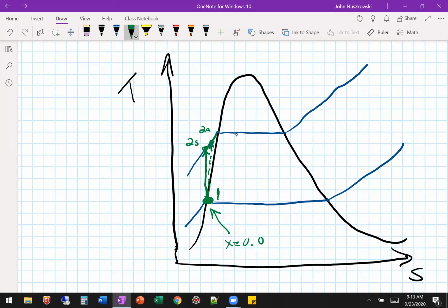Now when we go through the boiler, we're adding heat, we're adding energy, so that makes us add entropy, right? Along the same constant pressure, because we're going through a boiler. And we end up, actually, let's not go so far. Let's say we'll end up here, okay?